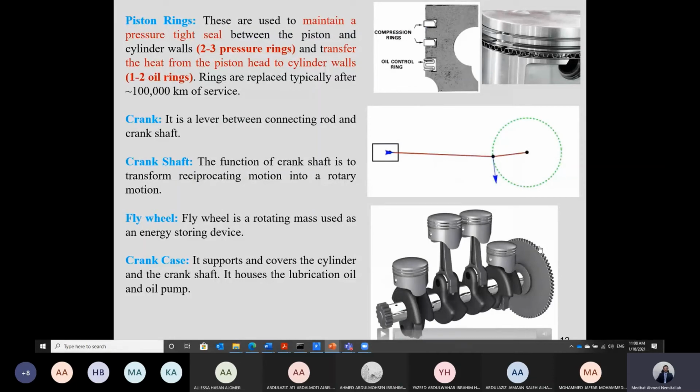Then this power is released with the inertia of the crankshaft to move the piston up and down during the other 3 strokes. So the function of the flywheel is to store the energy to be released from the crankshaft to move the piston while the other 3 strokes are going on, the strokes other than the power stroke. Is that clear, يا شباب?